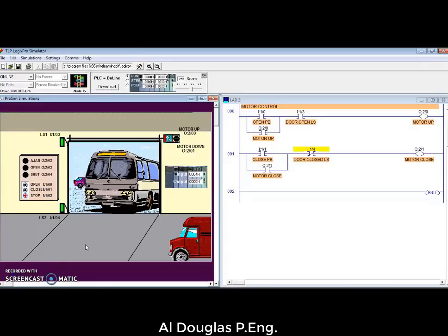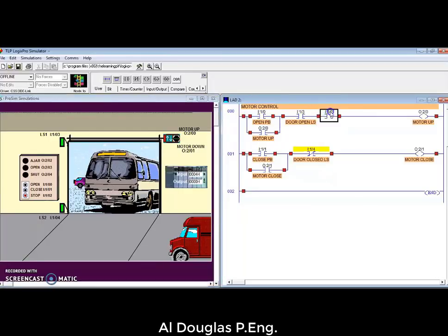As we drew out, we're going to modify our logic. We're going to add some more stopping conditions in here. We've decided that we're going to add the stop button. I believe if we hover over this, it will say it is a normally closed push button. I just know by looking at that description that I believe this is the correct contact. We'll know for sure when we actually try to run it. I'll call that stop PB.